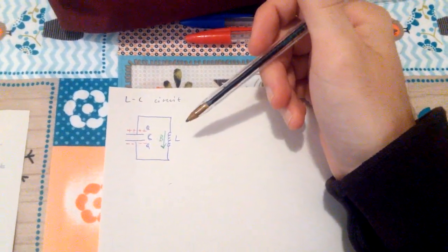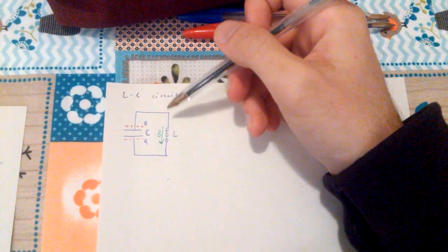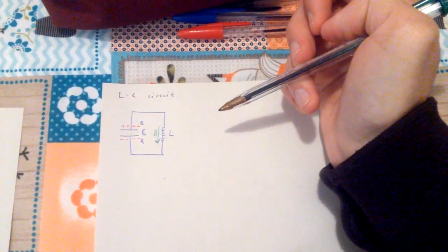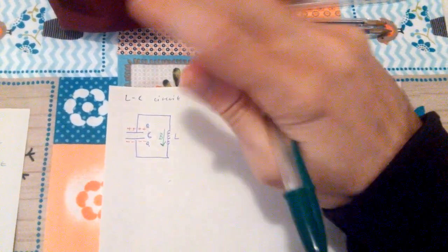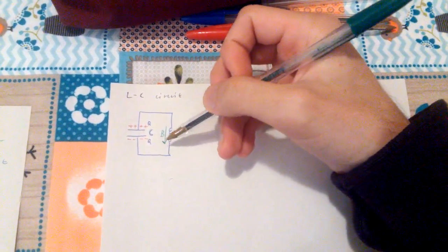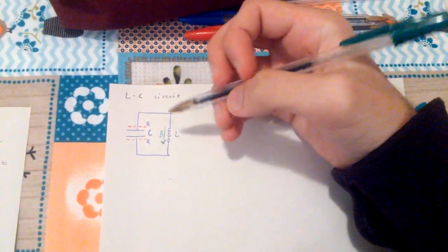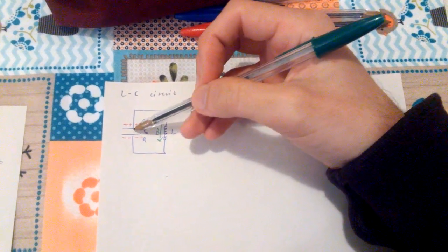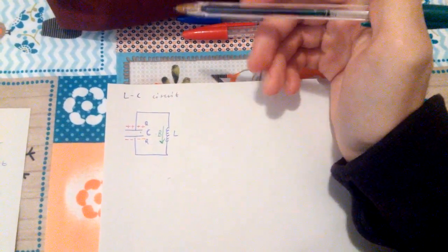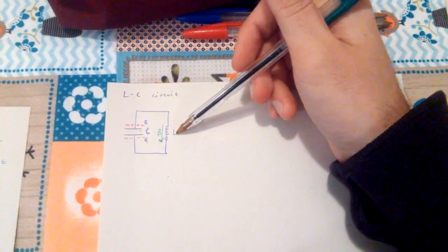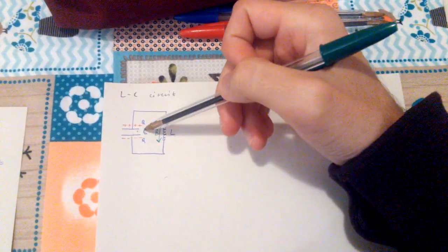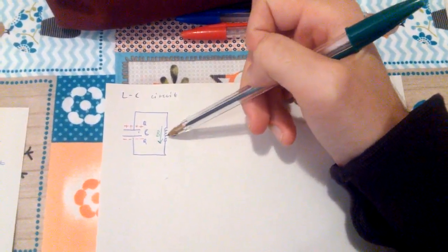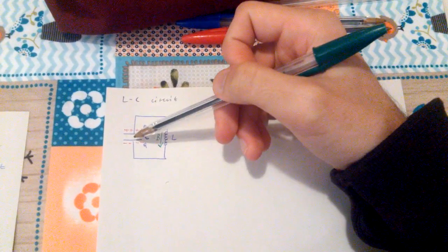But then the capacitor is going to be discharged, so the inductor is going to see a change in the magnetic field caused by the flow of current, and since nature hates change, it's going to try to fix that. It's going to try to induce a new current to keep everything as it was. So a new current is going to flow and it's going to go to the capacitor, and the capacitor is going to be charged. But in doing that, the inductor is going to be discharged and the cycle continues. So the capacitor effectively charges the inductor and the inductor charges the capacitor.